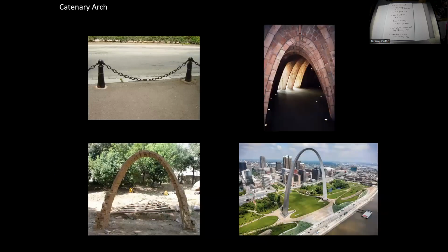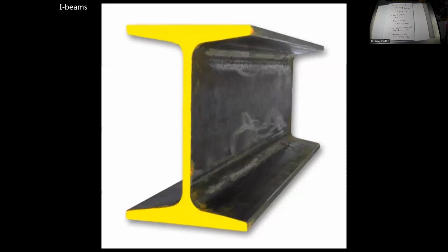Some other clues too you might pick up on, right? So if all the top is in compression, all the bottom is in tension. Yeah, that's just the specific example I'm picking, but just a simple example. All along the middle, it's going to transition. And in fact, there's some axis in the middle where there's no stress at all, right? Where it's like transitioning from tension to compression, right?